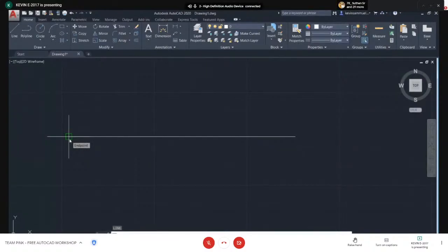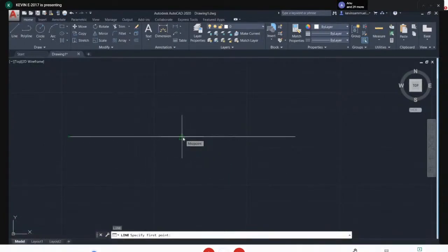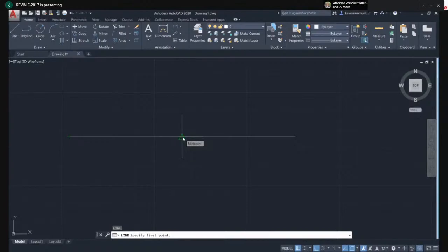So that box will determine my snapping position. And also if I press somewhere here, it will automatically show you that the object's midpoint is somewhere here. So it will be easy if you always keep the OSNAP settings on. If I turn off the OSNAP settings by pressing F3, F3 is the shortcut key to toggle that box, it will turn off my snap settings.